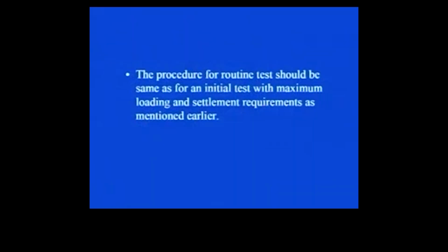The procedure for routine tests should be the same as for an initial test, with maximum loading and settlement requirements as mentioned earlier. So, all the details that we were discussing were related to initial tests. However, for routine tests also, exactly the same guidelines are to be followed. Now, this was the monotonic kind of load test that we were talking of.